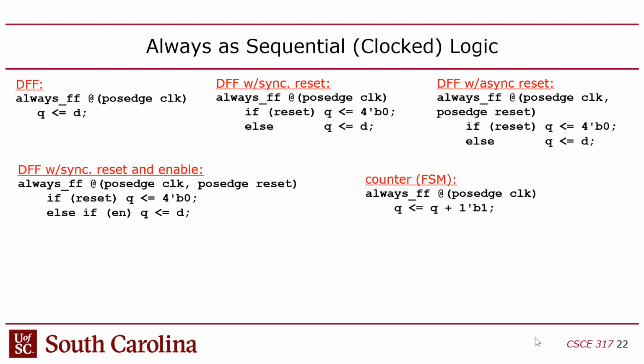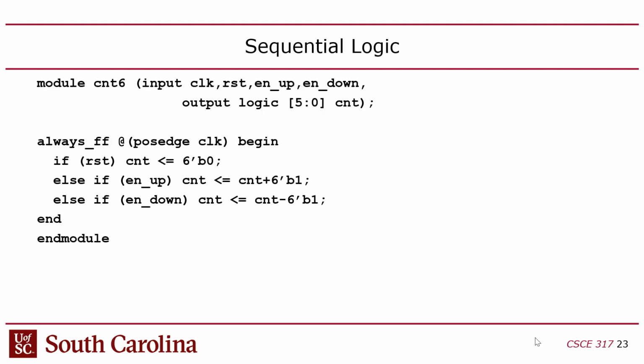I had to write a question for the 611 PhD qualifier exam last weekend. And the question I came up with was an SPI question. I asked the students to design an SPI bridge in Verilog. So you had a simplified interface on one side, and then on the other side it was SPI. And then you have to design a state machine, sequential logic, to go through the sequence of things that have to happen for an SPI transaction, or actually just an exchange in that case. So you can see why you'd have to design sequential logic if you want to build an SPI bridge.